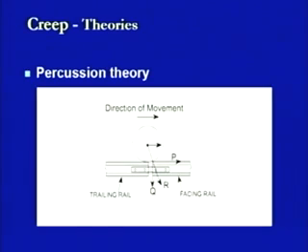Now, in this diagram, we are looking at the same aspect. In this case, this is one rail section which is being jointed along this rail section using the fish plates and the bolts. This is a wheel which has come to this location. Now, as soon as the circumference of this wheel touches the end of this rail end, it will be putting an impact in terms of this force R at this point.